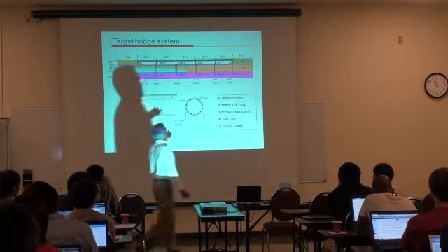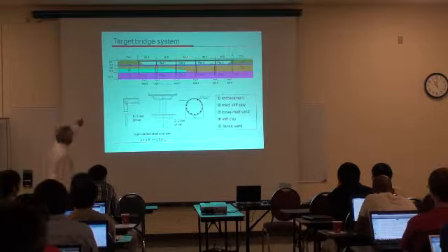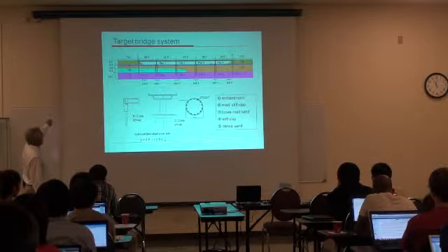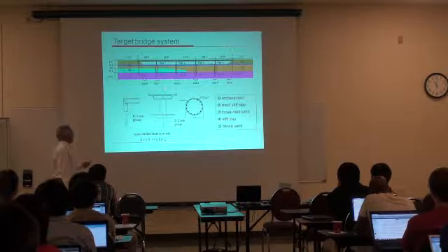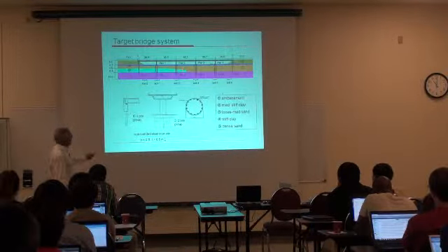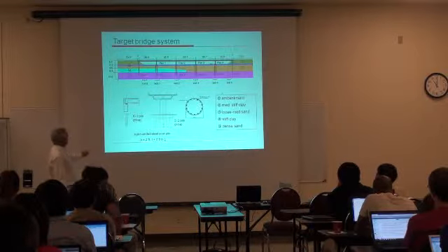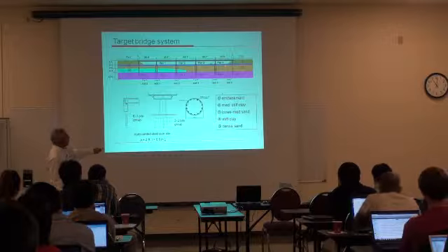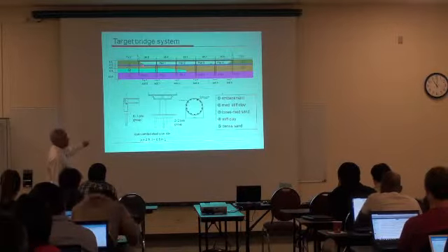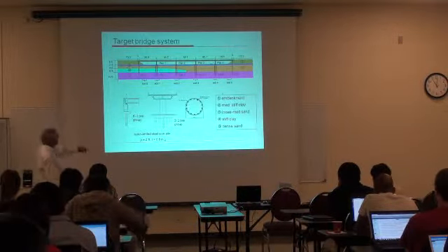Now we put the structure. This is the structure. This is the pile. These are the pile foundations. They are different at the abutments than at all the other locations. Here, the light blue represents a clay. This yellow represents a liquefiable soil, very thick here, not so thick here. And this is a very dense material.